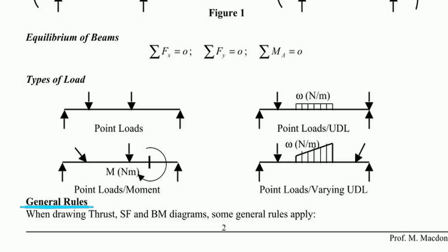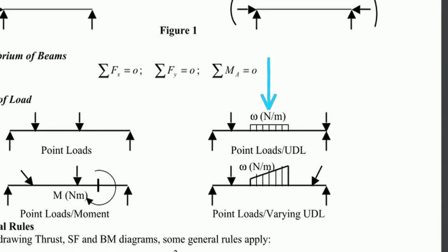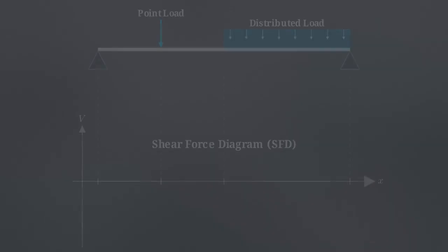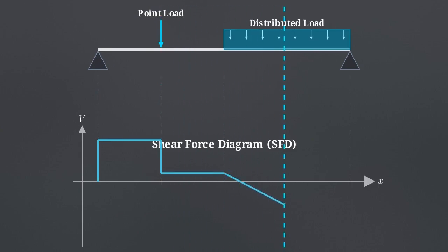This engineering reference outlines the general rules for calculating those forces. Because shear force fluctuates depending on where a load sits on the beam, engineers must track its magnitude continuously from one end to the other. They build a shear force diagram. With no new weight applied, it draws a flat horizontal line. A point load, like a train wheel, causes a sharp vertical step. Conversely, a distributed load, like the bridge deck, forms a smooth diagonal slope.